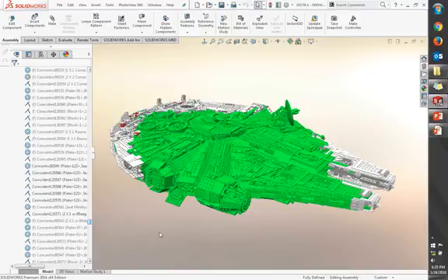Yeah, in this case I have different sub-assemblies. If I open up here, this is one of the subs, this is another sub over there, and then you have the main sub at the very top. So this is actually made up of two sub-assemblies right here. That's the point, though, that you're working on these small areas to really focus. Yeah, absolutely. But I still have to go to the main level and make sure that any changes I did at the sub-level are okay at the top level as well. Or else there's a rework on the floor, and we don't want that, right? I didn't know I needed to re-drill that hole.